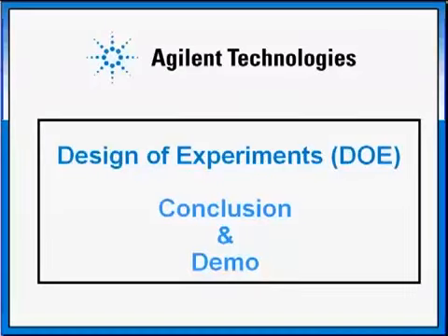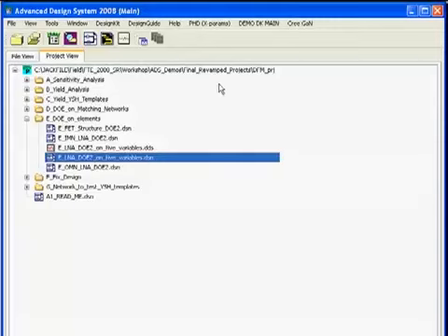I go to the main window in ADS and I open a project which is designed for a manufacturing project, DFM project, and notice in this folder, it's DOE on elements. I choose some elements, 5 variables in my amplifier, 5 different variables, and I want to run an experiment. So the number of experiments that ADS will run for me is 2 to the 5th, which is 32 different experiments to cover all the full factorial variable changes that I talked about in my introduction.